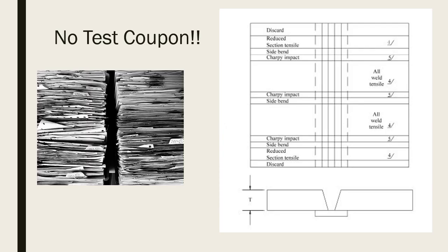The main advantage of using a pre-qualified weld procedure is you don't have to take the time and the money to run a test coupon and do a PQR and send it off to the lab and do all that work. You're going to have to write up some documentation for your WPS, but you don't have to qualify a procedure. You don't have to take all that time. So it could save you, potentially, a few $1,000 in time, effort, and whatnot to run a test coupon, do a PQR, send it out to the lab, and then write up a WPS.